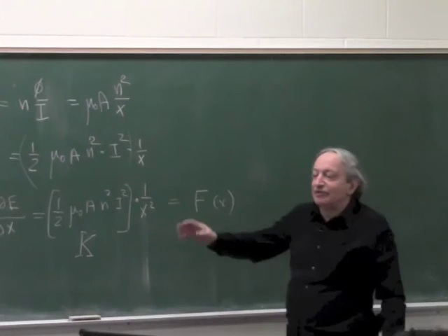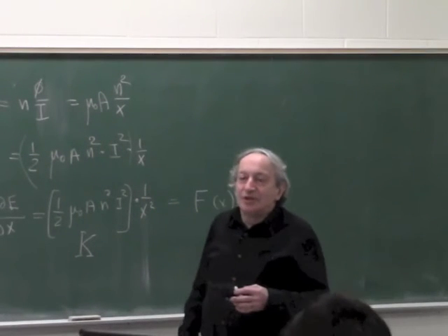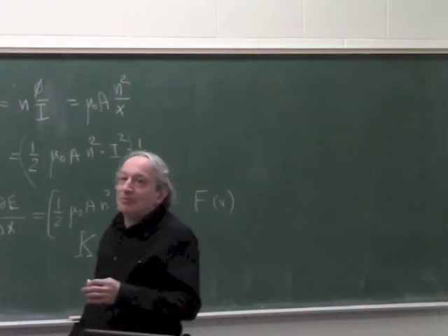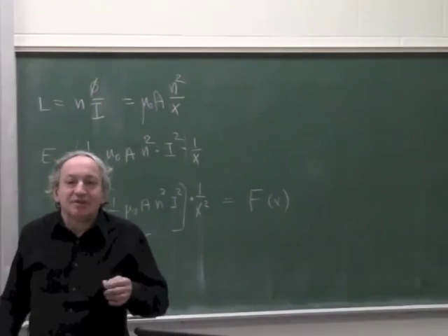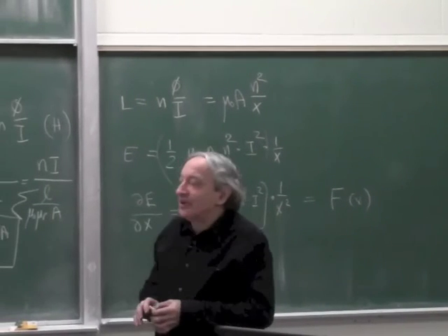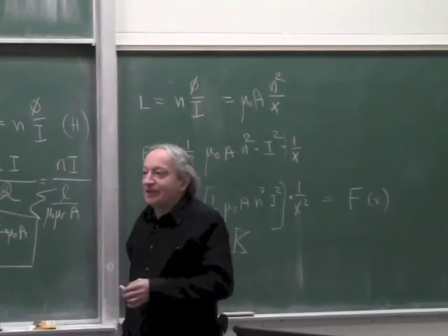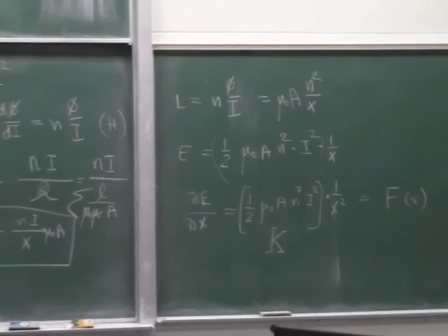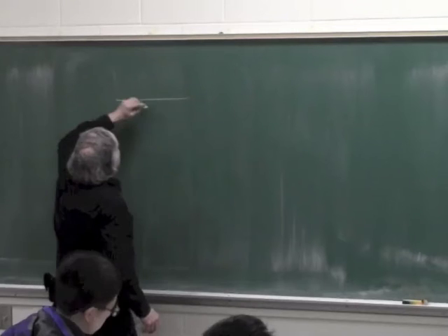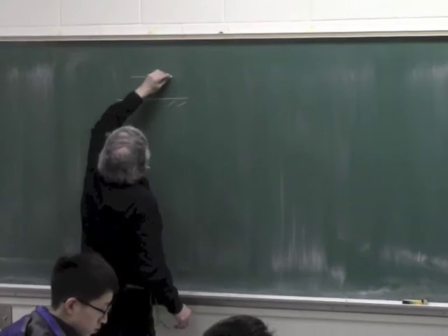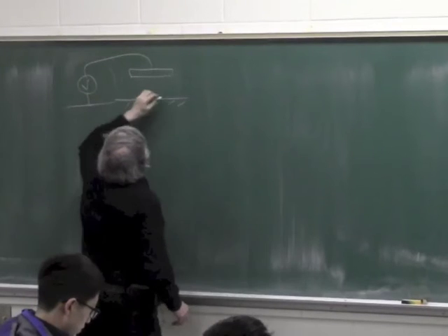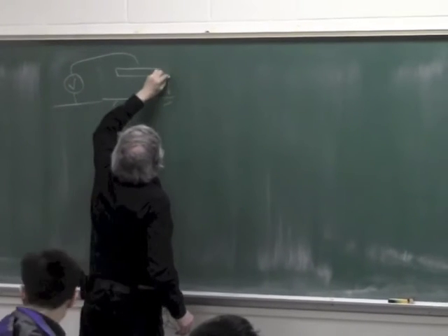Because the same type of derivation you use for many types of actuators, especially these nonlinear actuators, where it's not so simple. In a moving coil, the derivation was very simple. We said BLI, that's the whole derivation, right? But in a nonlinear actuator, you have to derive the force this way. So let's do a quick other exercise, do the same derivation for a capacitive actuator. Let's say we have a ground plate, a capacitive plate, we connect it to a voltage. This time it's voltage, not current. You have an electric field here and you have an attraction force.